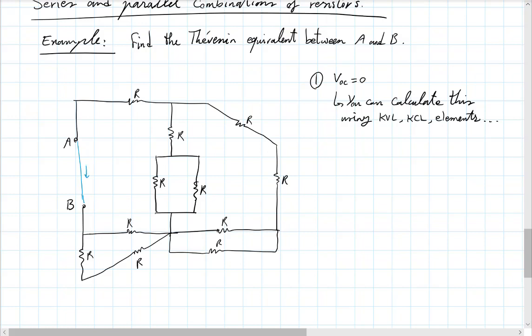Okay, so that would be your second piece of data, the short circuit current. And again, you can calculate it in the same manner if you're uncomfortable. Notice that this is a different circuit compared to the one that did not have this wire. Okay, so you have the open circuit voltage, which is 0, and the short circuit current, which is 0.